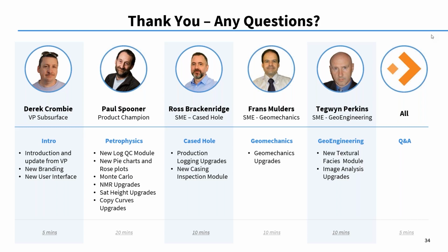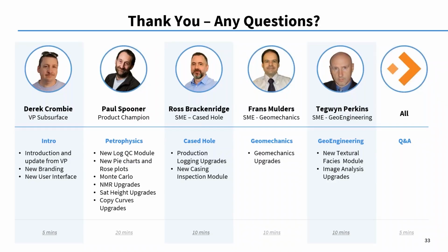So the standalone plots are for if you don't want to use the VSW module, but you still want to do something complicated like involve mineralogy in your porosity water saturation calculations. Frankly, that's exactly what the VSW module has been written to do. So I would just bring my log curves, density neutron sonic, directly into VSW and hopefully a PE as well. And then I can use the multi-mineral option in VSW. That's the way I would do that.